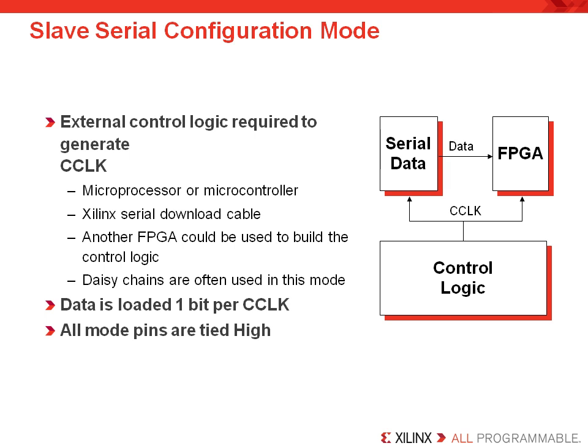The advantage is that the user could store the bit streams for multiple FPGAs in one external memory resource other than a flash PROM, and depending upon the application, this may be beneficial as well as cost effective. Note that this configuration mode is rather slow, only loading data 1 bit per clock.